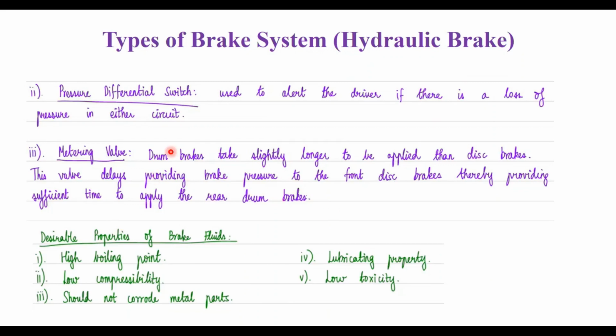And these are the desirable properties of brake fluids. It should have a high boiling point and low compressibility. It should not corrode the metal parts. It should lubricate properly. It should have low toxicity.